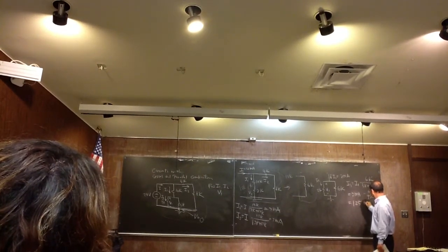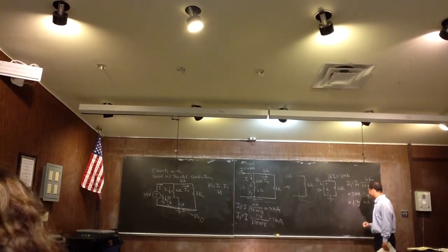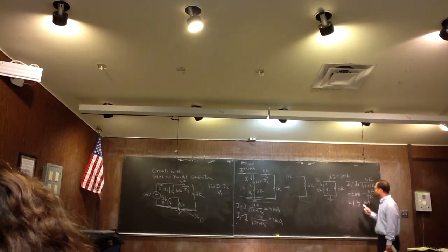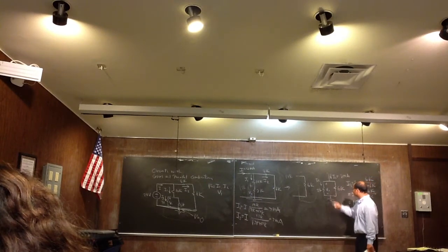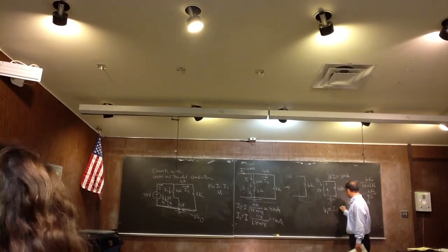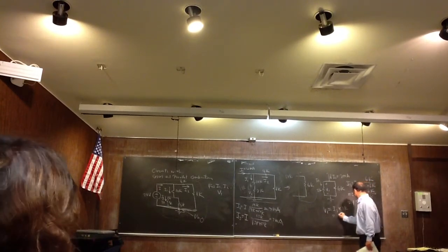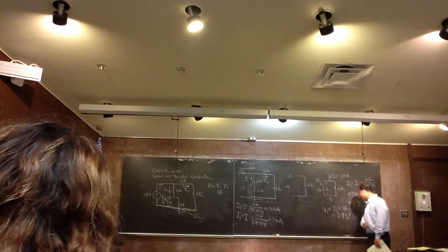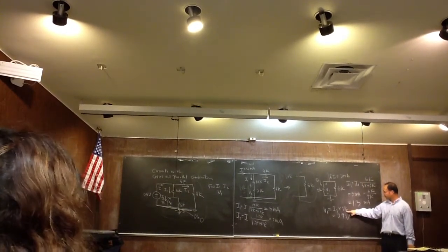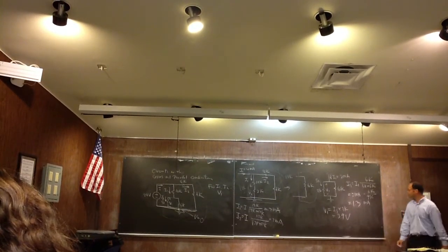2.5, yeah? 1.3. Well, at least I was close. Okay. Then, what is V1? Then you can use Ohm's law, right? V1 is equal to I3 times 3K, so it's equal to 3.9 volts. Milliamp times K cancel each other. This is 10 to the minus 3, this is 10 to the 3. 3.9 volts.